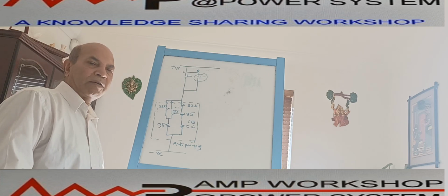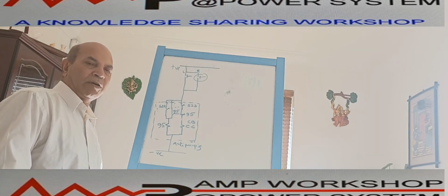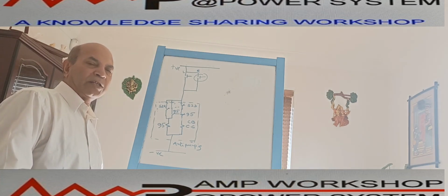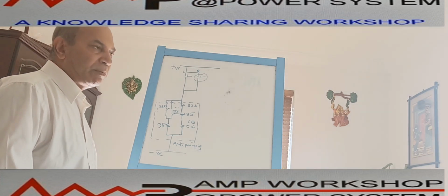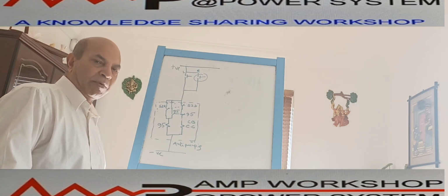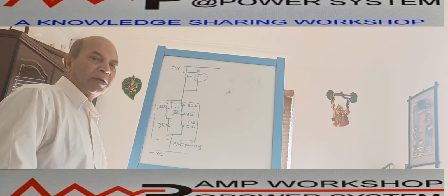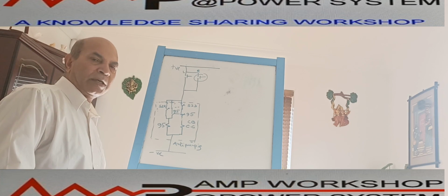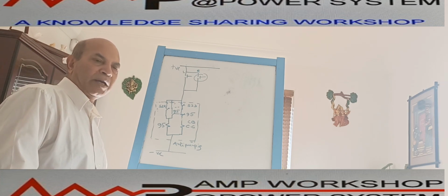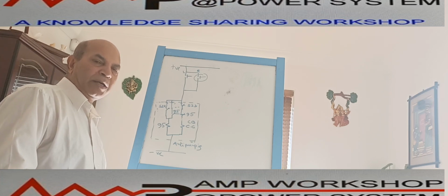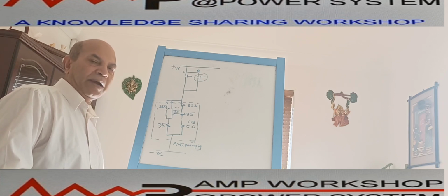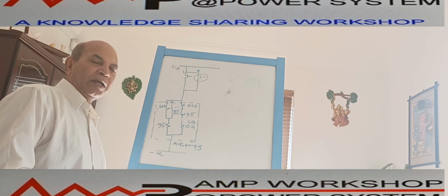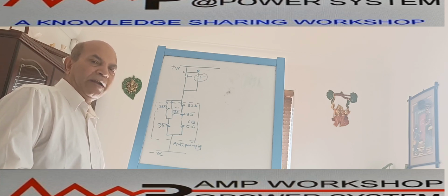As I received the comment from our valuable friends, I thought to highlight this point with another small video so that it will be more clear. This part of the schematics is about whether the command is a short time command, given to a breaker instantly so that the breaker gets closed, and then whether the command is maintained or disconnected. To capture this part, we discuss it as the anti-pumping circuit or anti-pumping feature.